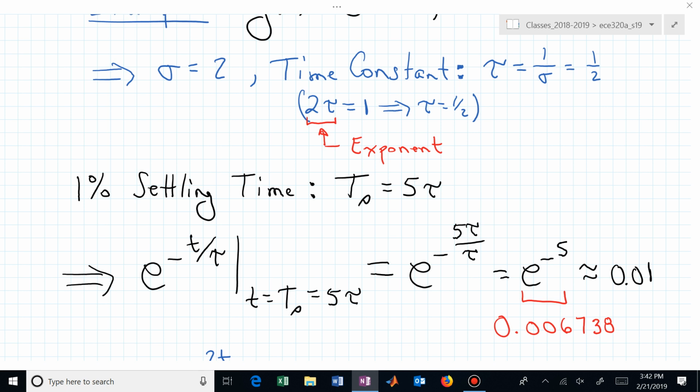And I sort of joke, I never joke around, but if I say when is infinity small, well, in electrical engineering, infinity is actually 5 time constants, and if your time constant is 1 millisecond, in 5 milliseconds, you've now reached an infinite length of time, effectively, because you've now decayed away. So infinity, well, it's not very big. It's 5 milliseconds. Yeah. So is that clear?